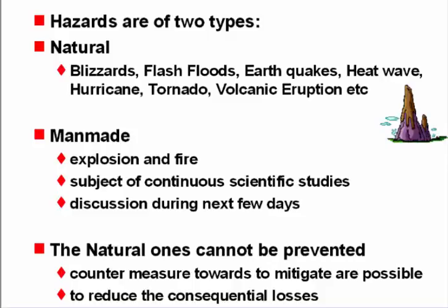There are all sorts of man-made hazards that we introduce into our working environment, and we'll be concentrating mainly on the use of flammable gases and dusts. Most dusts are in fact incendiary. They will burn or blow up or explode if given sufficient energy or enough heat. So even sugar, corn flour and normal household dusts will combust given the right environment. So we're going to be looking at trying to contain to an absolute minimum the risk of explosion or fire occurring due to the release of a potentially hazardous substance.